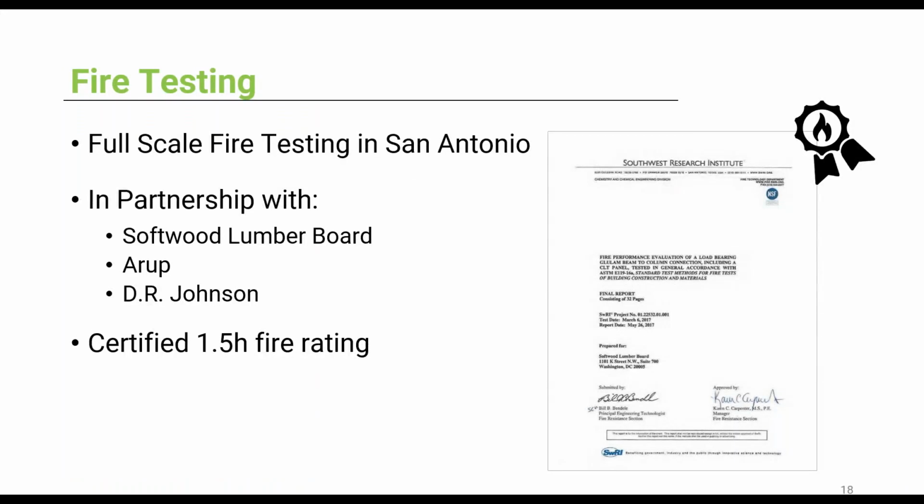We've done a full-scale, fully loaded fire testing in San Antonio, Texas, in partnership with the Softwood Lumber Board, AWC, and DR Johnson. And the Southwest Research Institute published a separate report, and it certified the beam hanger system with 1.5 hours of fire rating.